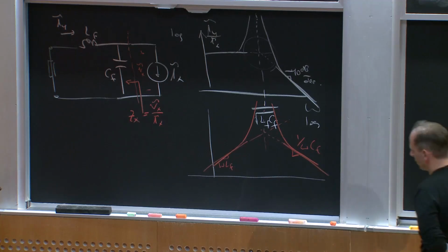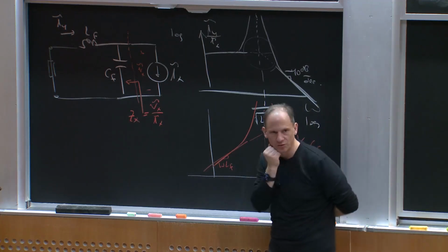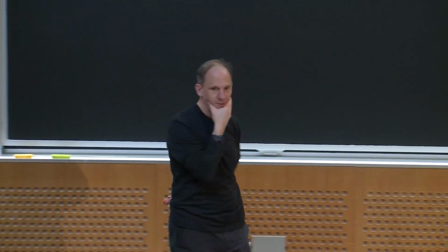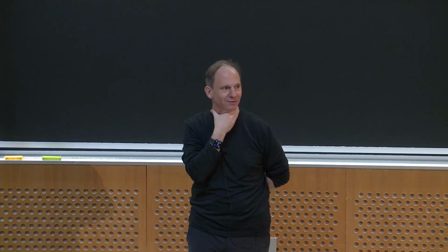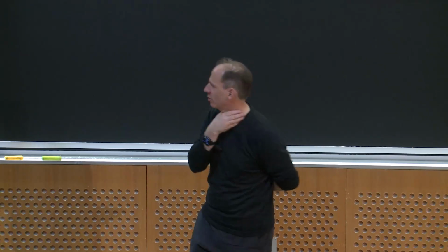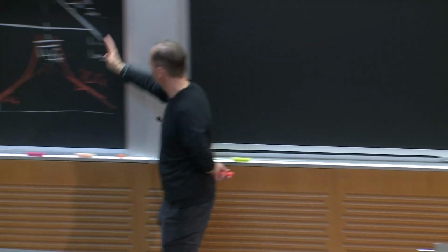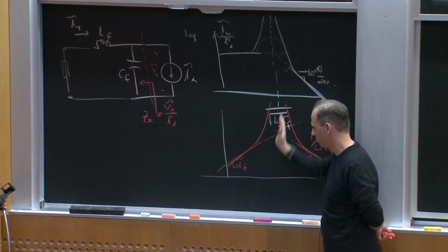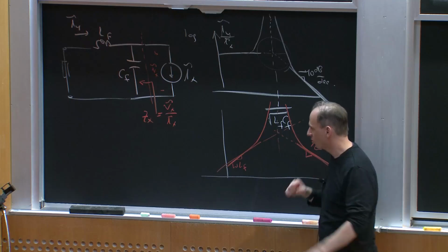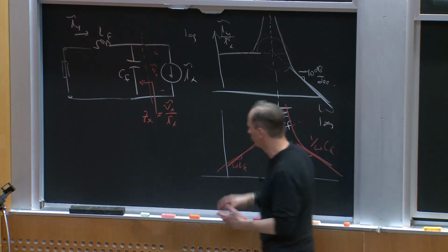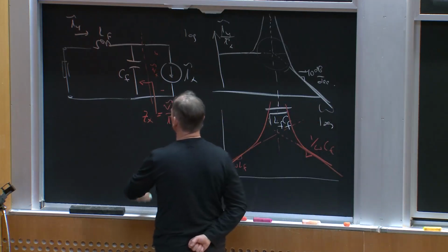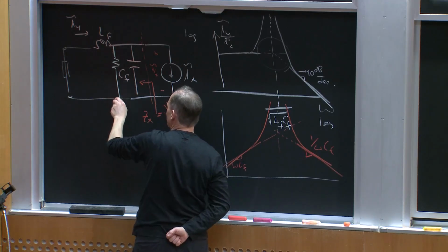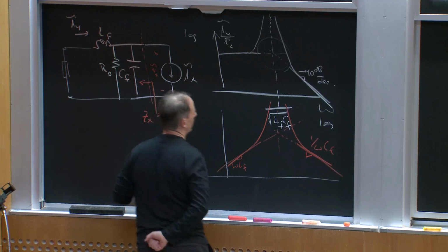So what would I do about that? What would be the kind of natural thing to do? You better put a damping leg on your filter, right? So while we're using this filter way out here to cut off ripple from the converter, I also have to think about what it's going to do here. Now, the most natural thing to think about doing in a filter is maybe just putting a resistor. Maybe I could put a resistor, I'll call it a damping resistor, RD, right here.